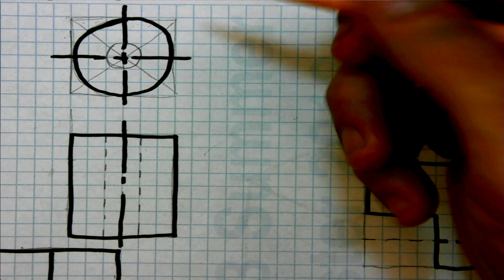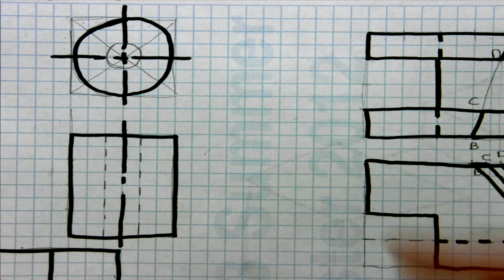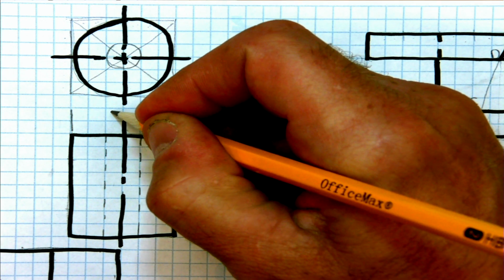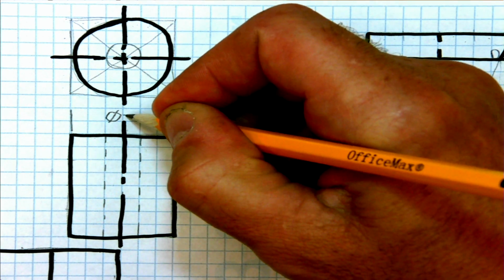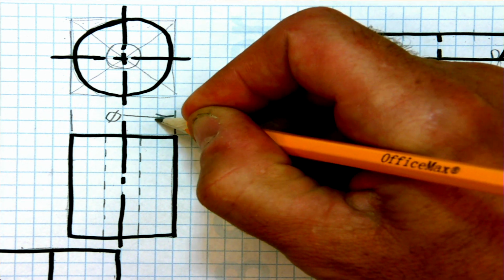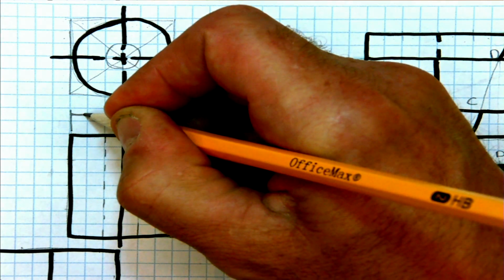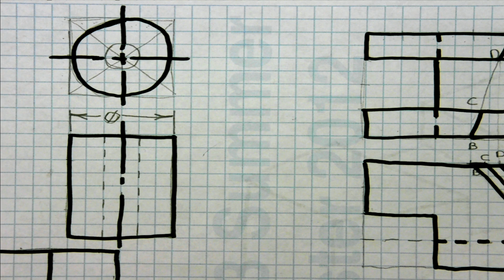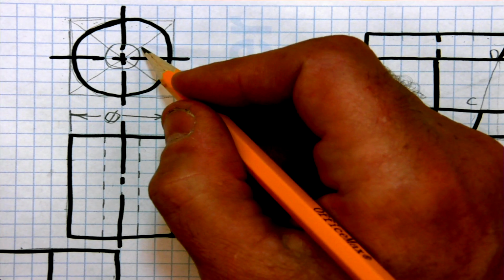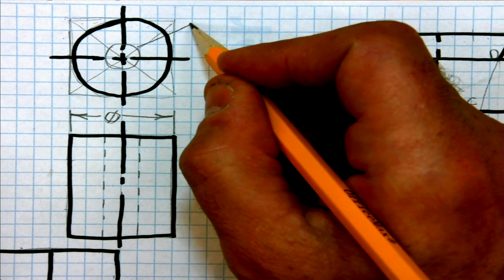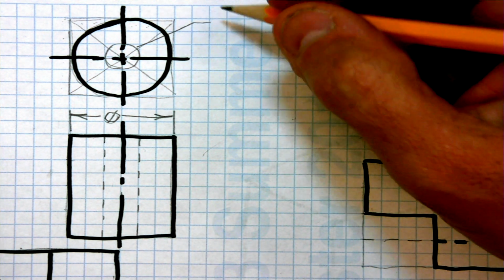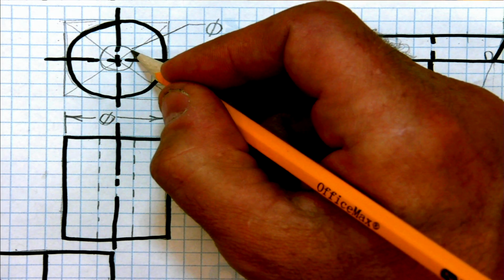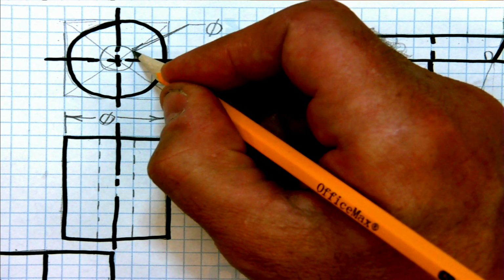So now let's go ahead and dimension this feature here again, okay? So again, this is a positive cylinder, so I'm putting the diameter symbol between the views whenever possible. On positive geometry, you put the dimensions between the views and you put the diameter symbol on the rectangular feature. On a negative cylinder, you put the annotation, which is non-graphic stuff on drawings, engineering graphics, and you would just put the diameter here. Okay, the arrow is pointing towards the center of this thing, right out in that direction there.